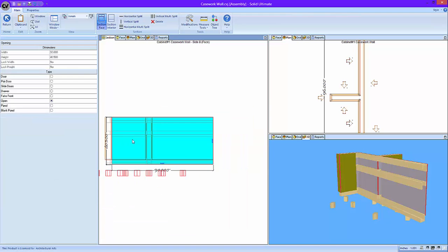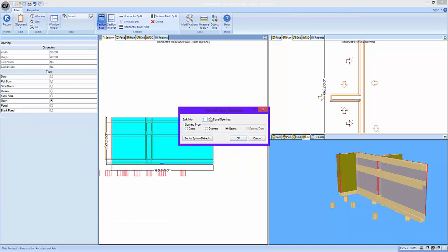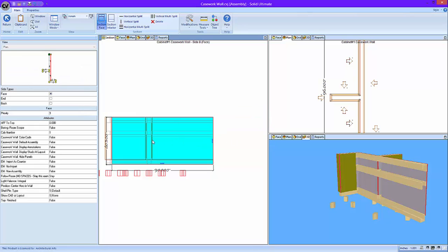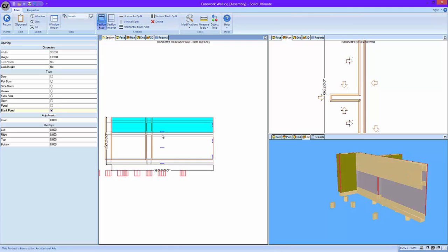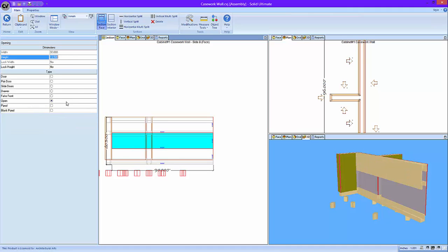The inside section is going to be a little different. Generally speaking, we're going to split that into 3 sections. The top of which we're going to call a blank panel because it'll be probably tack or something. The middle of which is just an open. And it's going to be the countertop thickness plus a 16th just for some clearance. And we'll lock that so it can't ever change.